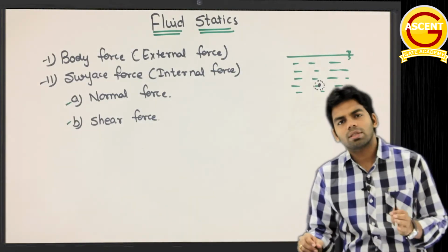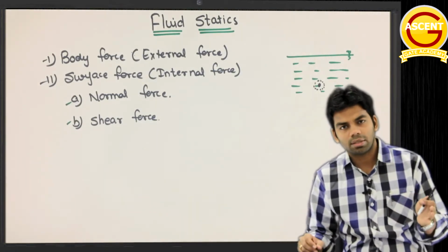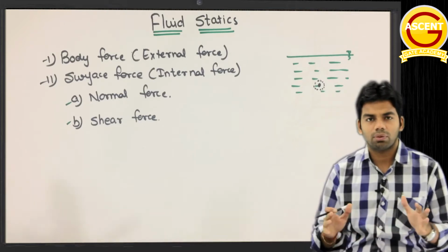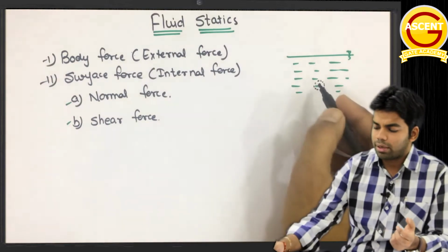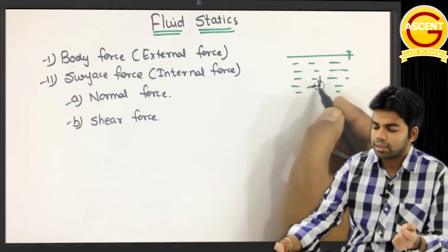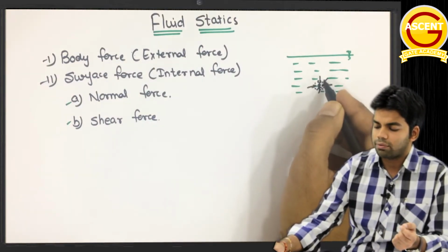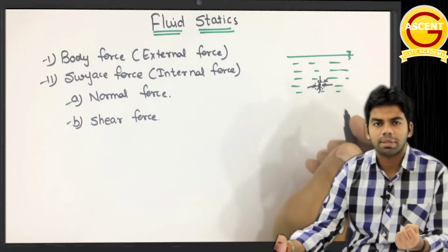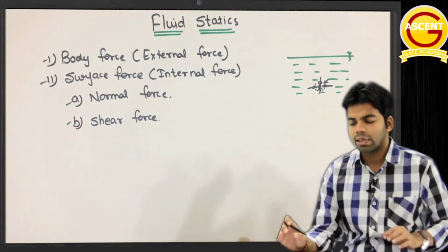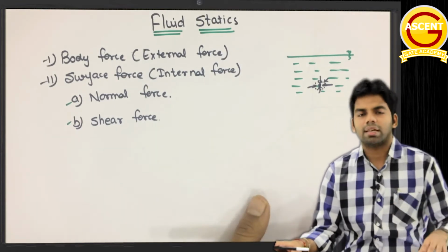Obviously, because this is a fluid at rest, no frictional force will act. Second thing, only compressive force will act in this element and not any tensile force, because the pressure will be acting. Pressure is always compressive in nature, so only compressive force will act in this particular fluid element and not the tensile force.